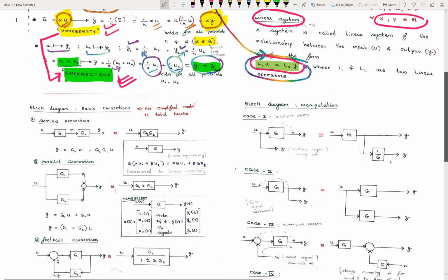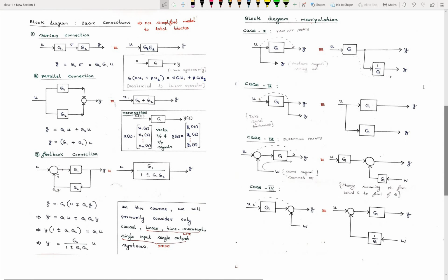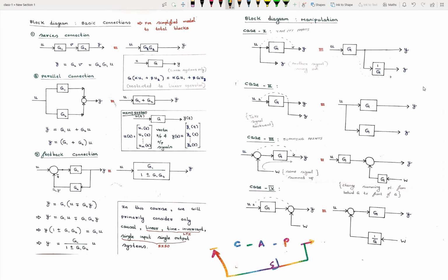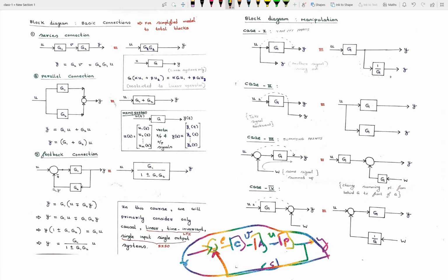Now we go for block diagram reduction. See, in a control system, basically we have one controller, an actuator, and one plant. In feedback, suppose we take the output y in feedback here, we have a sensor and some summing point. So this is how we represent it, right? In a basic control system, we have some input here, reference r, output y, some error signal here, some input signal u here, some v here. So there are many blocks involved in a classical feedback control system.